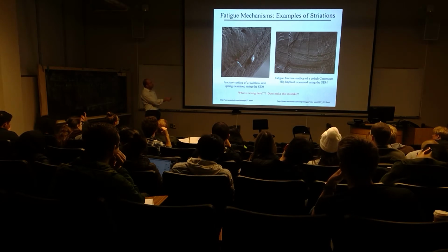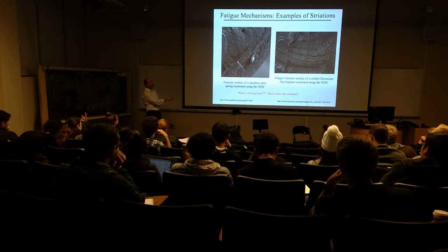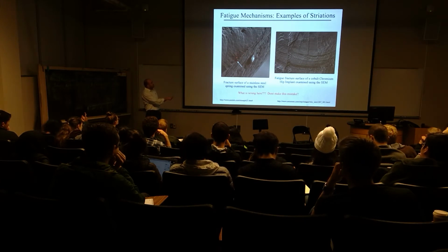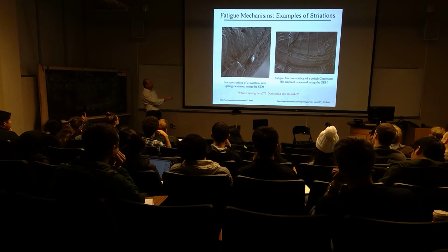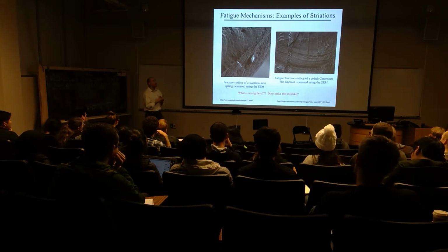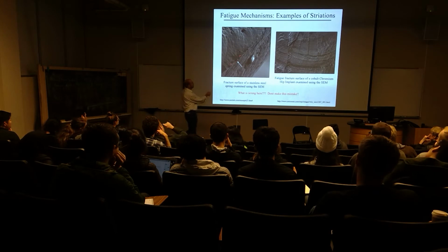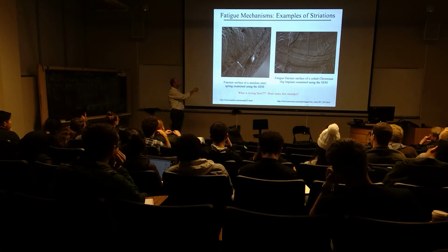So when the crack is just starting to undergo cyclic deformation or cyclic extension, the distance between the adjacent striations becomes very, very small, and then also, depending on the ductility and the amount of the rubbing in the fatigue cycle, they potentially get washed out. So here's the start area, and you'll see the fatigue striations only extend and get really well defined as we go further and further from the origin point on this particular component.